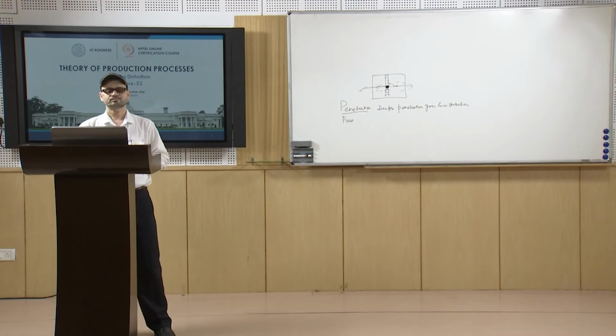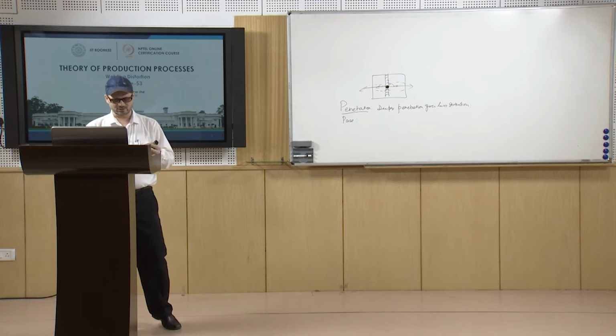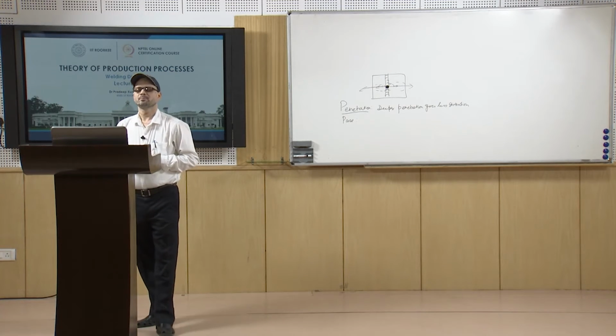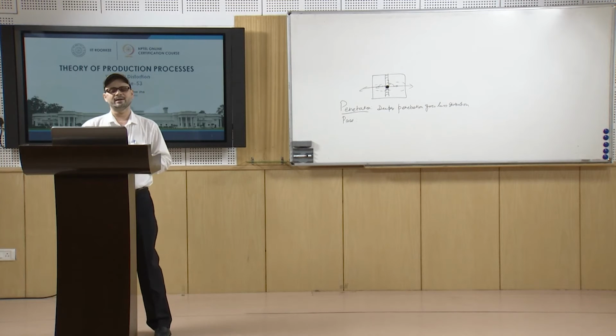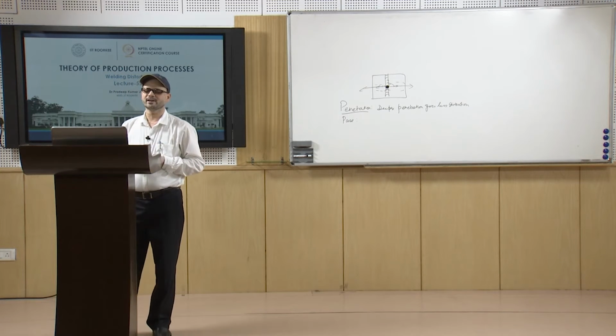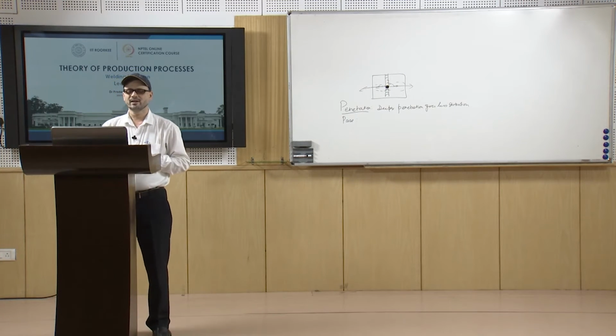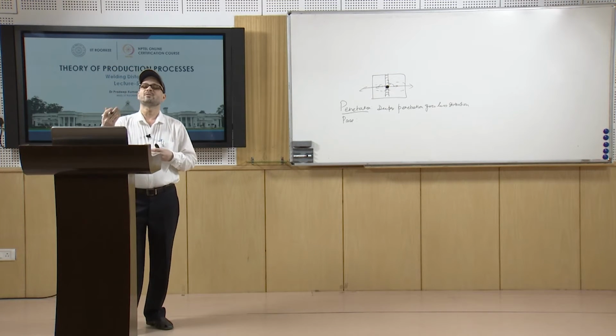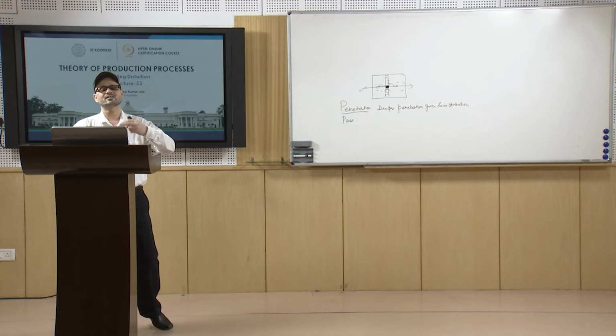Then you can calculate the amount of this longitudinal bending, and normally it depends upon the cross sectional area of the weld, then the distance from the CG to the outermost fiber. That is another parameter.